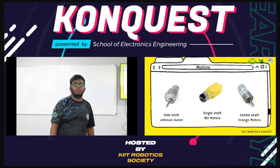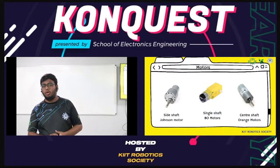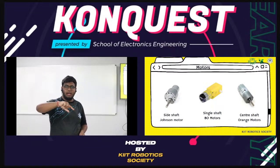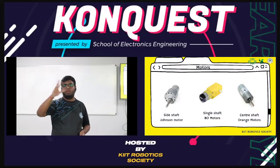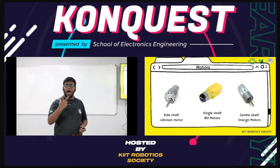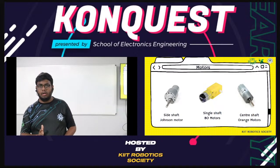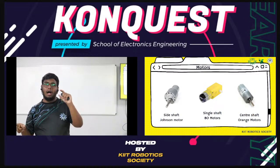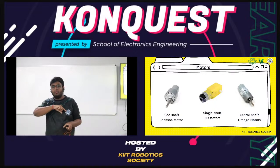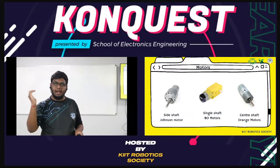Now, there are two kinds of motors. We are not going deep, just an overview. One is the center shaft motor and the other one is the side shaft motor. What is the basic difference between center shaft and side shaft? Center shaft has a high RPM but somewhat low torque. Side shaft has sufficient RPM but high torque. Now you have to see which kind of motor you have to choose to tackle the obstacles.